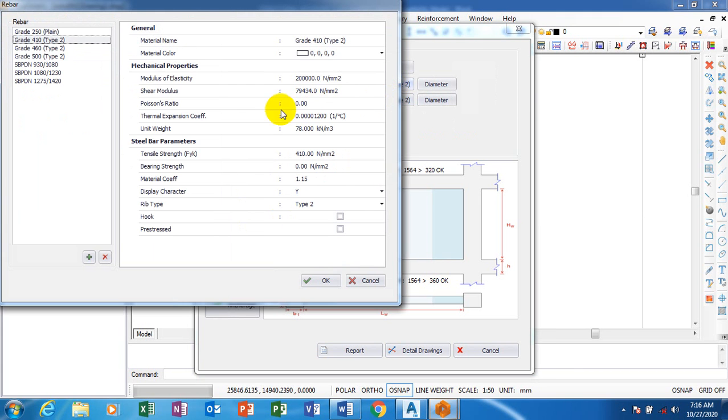And then this is the grade for steel, the characteristic strength of the steel, because we are using BS 8110. So for grade of steel, 410 is the default parameter, which we are going to maintain. You don't really need to tamper with that. If we switch this, you can see the parameters change based on the strength of the concrete.